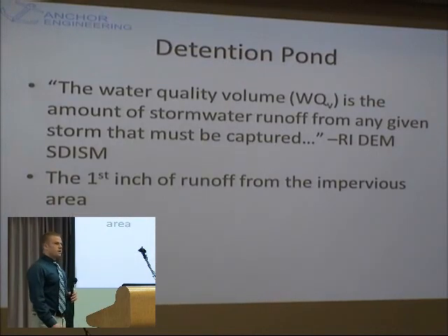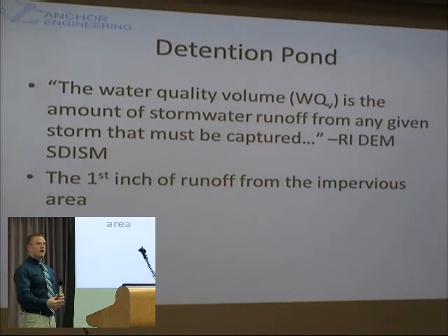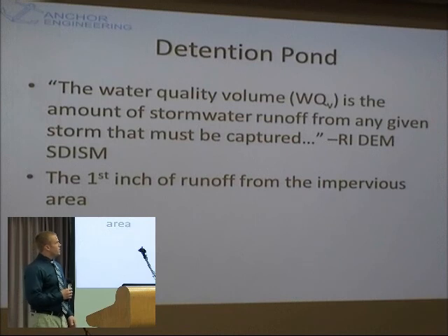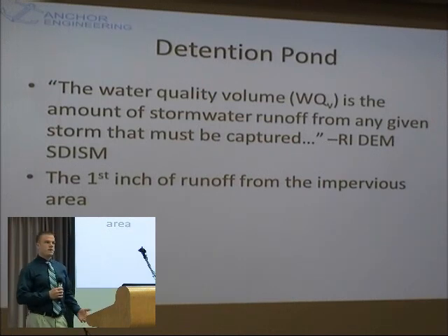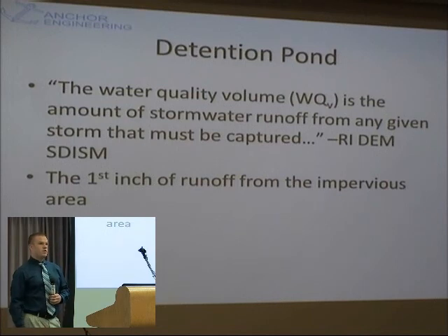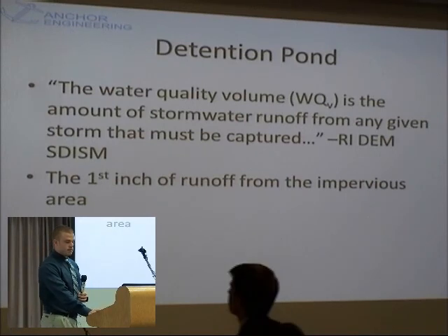The detention pond is required for treatment of the water quality volume as outlined in the manual I mentioned earlier. You need to treat the first 1 inch of runoff. To calculate this, you multiply 1 inch by the impervious area, which was the roadway. We needed to account for 3,000 cubic feet of treatment. Our pond is designed to hold 3,300 cubic feet, so we exceed that value. Next, Ben Pickering is going to talk about the bridge design.